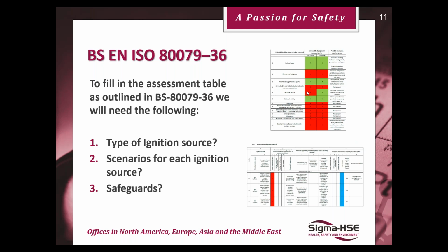So the bearing could get hot during normal operation, it could deform, and then it could lead to a misalignment of a shaft inside this rotary equipment, and possibly the shaft could even break off. So there's 3 different types of scenarios that are outlined, and each scenario, as mentioned in step 3, will need a safeguard. Your safeguard could usually be a maintenance procedure, or instrumentation like temperature monitoring, vibrational analysis, sensors, or even inadvertent sensors can be used in an equipment. But I will talk about this later on in the slide.